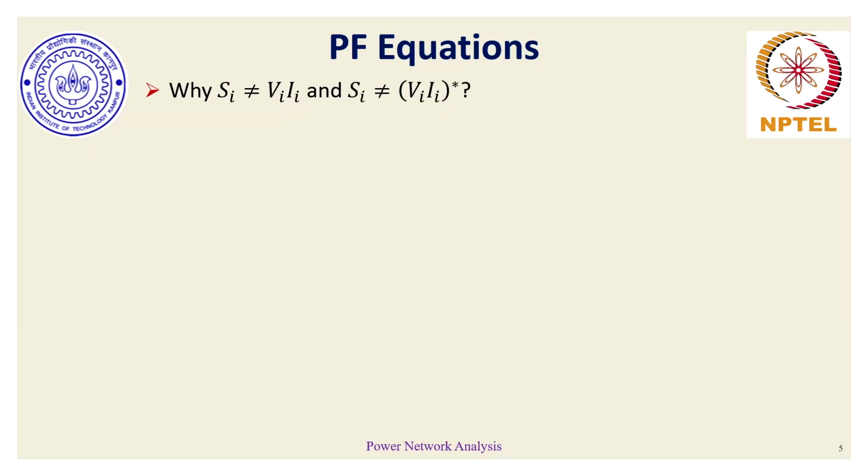If you recollect the definition of real power, it is actually the average of instantaneous power. And when we say average power, it has to be a quantity which is independent of time. Remember, our voltage and current phasors can have their own time domain representations. To convert a time domain signal into the frequency domain, we have to choose a frequency component as a phasor, where sine omega t or cos omega t, with omega being the source frequency, is chosen as the reference.